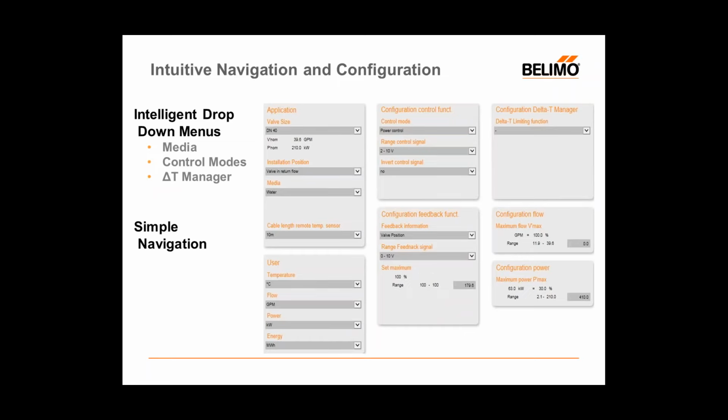If you have to change the remote temperature sensor length, so if you have a temp sensor that's either too long or not long enough, maybe it's too long and you need a shorter temp sensor for the remote sensor or the supply temperature sensor. These are all PT1000 RTD temp sensors, so the cable length is critical and cannot be cut. However, we sell or provide the remote temp sensor with different specific cable lengths. If you do go in and change that remote sensor cable length, you'll have to go in and reconfigure it in WebView to get the accurate temperature reading.